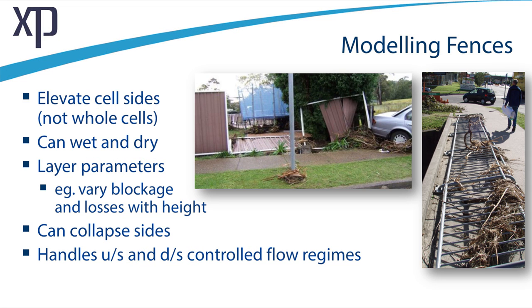Modelling fences. As we showed before with blocking the building size, you can actually change the elevation of your cell size, and modelling a fence is done in the same or similar manner. You do not have to adjust your whole cell. So these cell sizes can wet and dry, and you can actually vary your parameters such as blockage and losses with height by using the layered flow constriction feature.